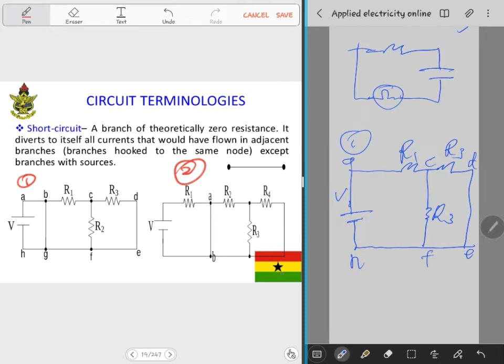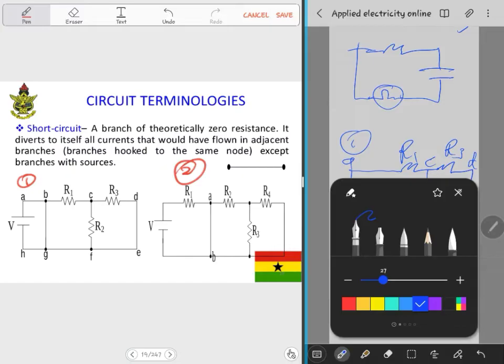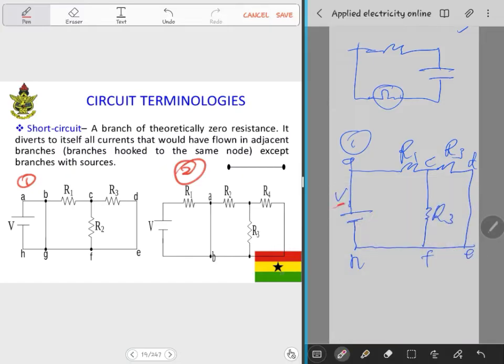So generally, there's a voltage source in the circuit, right? If current were to be flowing, it will move from here because there's a positive terminal and negative terminal, right? So it will move in this direction and then come here, pass through this, and when I get here, the same current will split. So if here is current, I1, this is another current, let's say I2, and this could be another current I3. Meaning that this I1 will be equal to I2 plus I3, right?